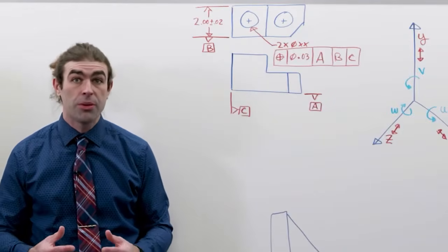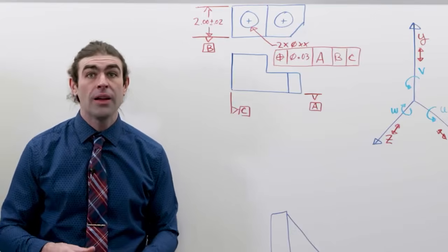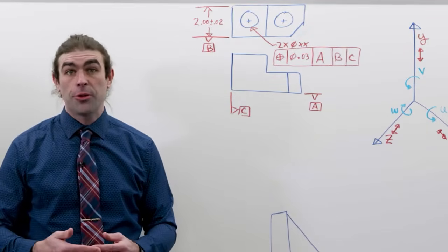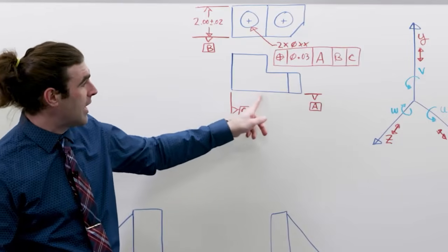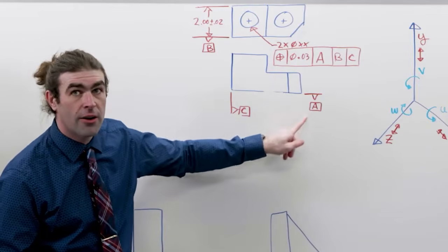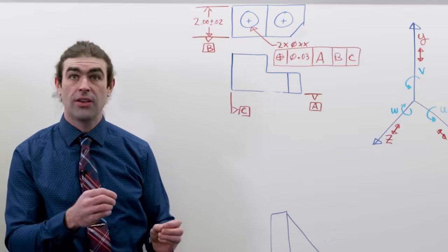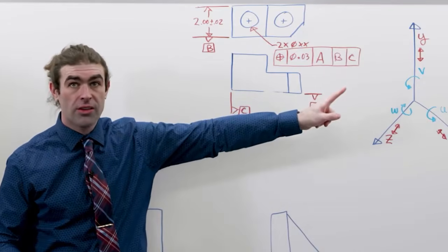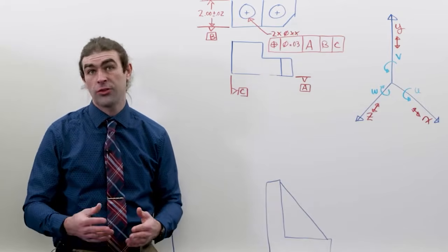Now I want to talk about some of the ways datums are identified on the drawing. If I didn't go through it before, the terminology with this: a datum is a perfect line, point, or plane. A datum feature is a physical portion of the part. So this plane is our datum feature. The datum feature symbol is this little guy, the letter in a box with a little triangle pointed to something. It tells you which feature is a datum. The datum reference is in the feature control frame, and tells you what order to use your datums and at what material condition the datums apply. And then the datum feature simulator is just your inspection equipment.